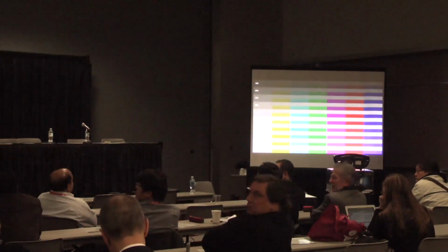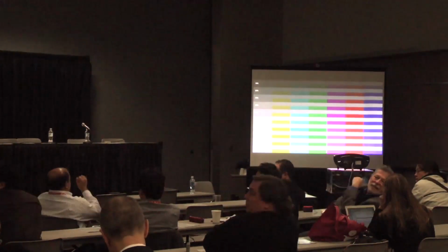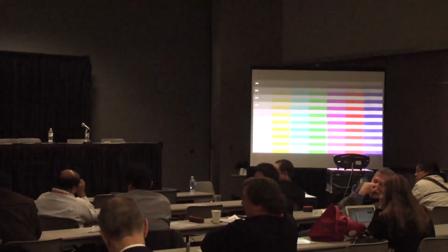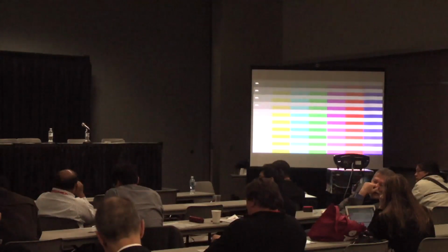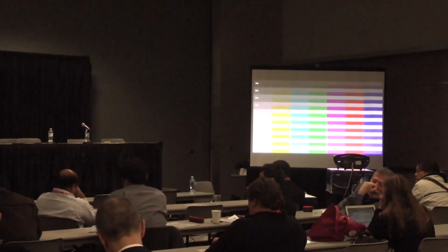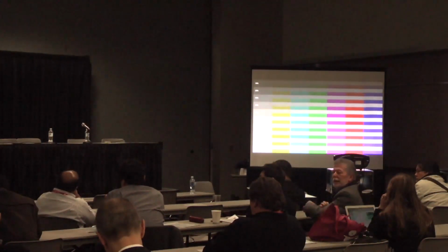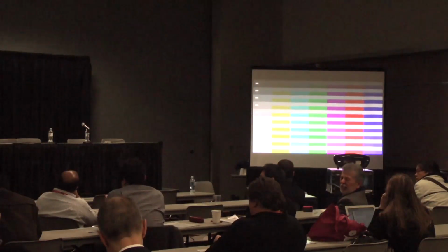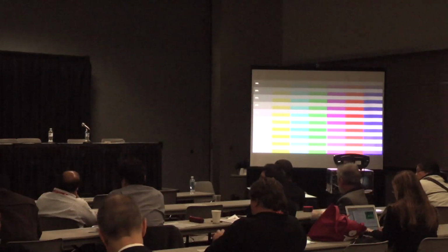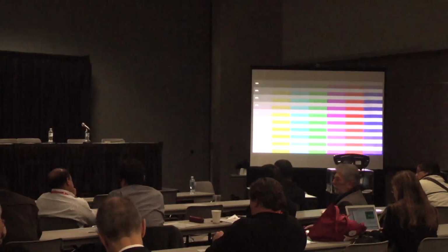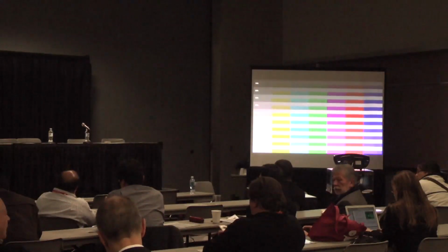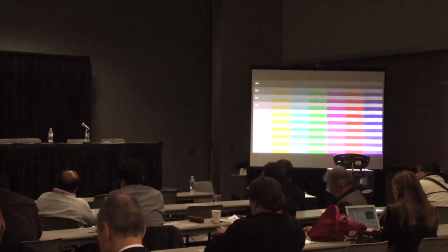Now back to stereoscopic and your measurement picture for the crosstalk. Have you ever thought about putting different measurement zones, because the crosstalk is maybe not equal over the screen, especially on LCDs? We discovered that due to the different heat on the screen, you have different crosstalks over the screen. The answer to that is yes. The moment I created the first pattern, I realized it didn't work.